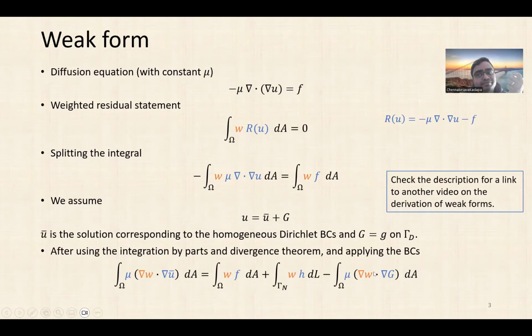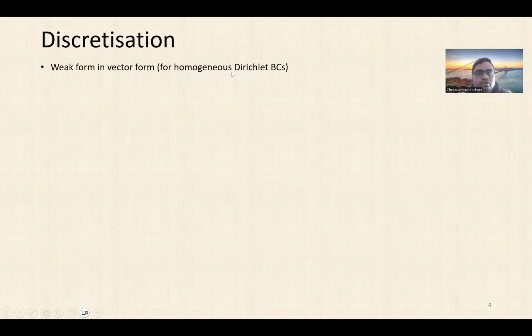Okay, the application of Dirichlet boundary conditions is going to be the same. That is, we multiply the column in the stiffness matrix with the corresponding specified value for that degree of freedom. So the application is going to be the same. In order to avoid the derivation further, I am going to assume homogeneous Dirichlet boundary condition, that is U equals 0 on the boundary.